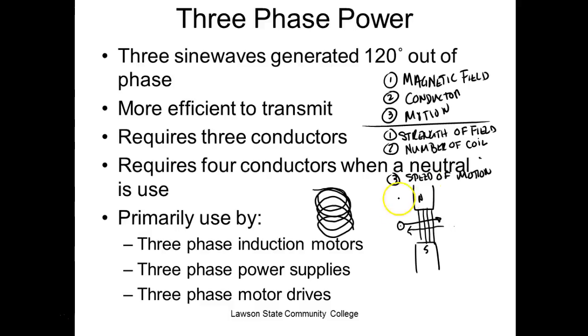So if I go back and forth, or if I come up here and spin this, like this, then out here it's moving in the same direction. It's not cutting the wire, so we get 0 volts out. We get our maximum voltage right here when this is perpendicular, and then over here we change direction. So what would happen is this guy right here would generate one of these. It would generate a sine wave, which is AC. And I guess this is where the 360 electric degrees came from, because originally when you went through 2 poles, you generated one sine wave.